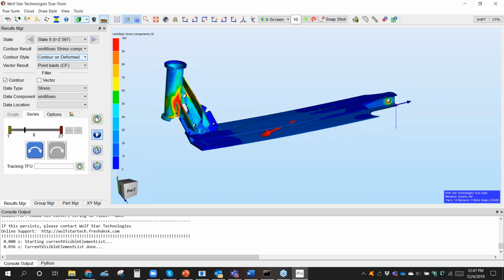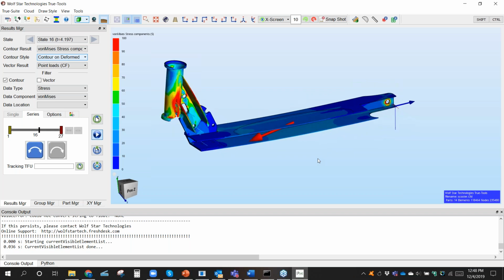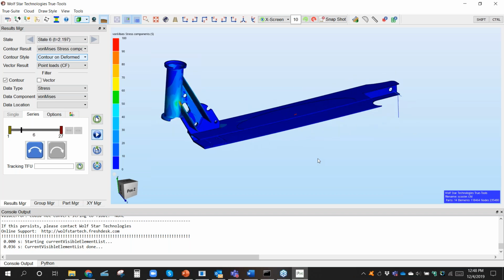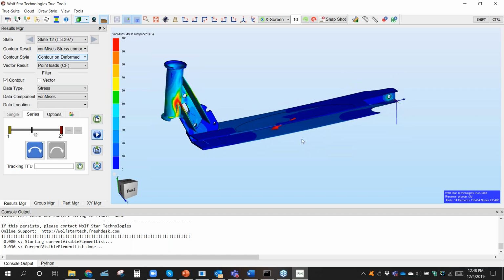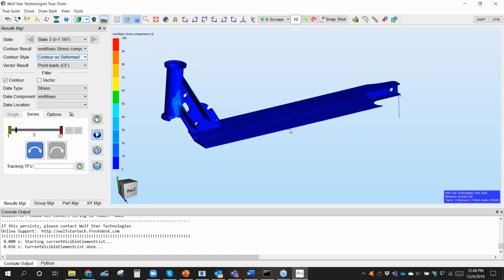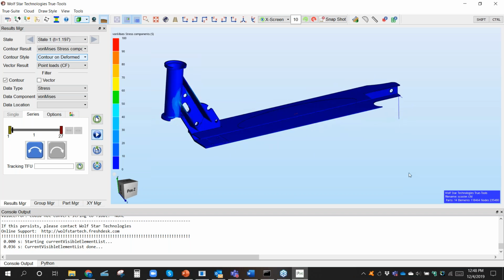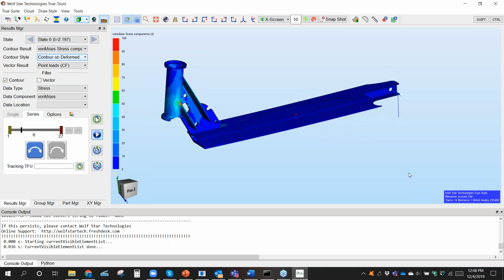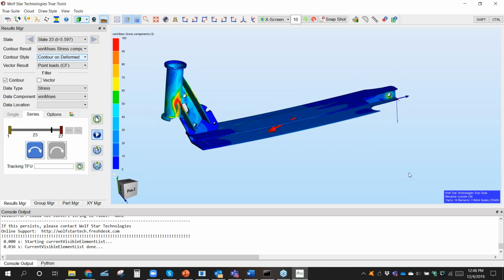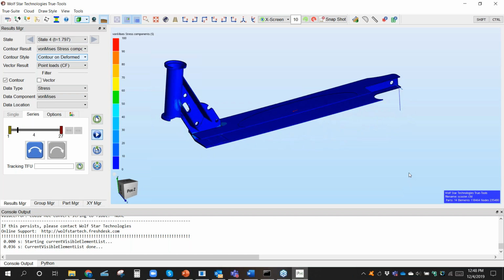Well, this Razor scooter is a perfect example of contact nonlinearities, right? So the way we deal with a contact nonlinearity is basically you introduce a unit load at the point of contact. So in my example here, my nonlinearity is at the foot, right? The foot can go on or off. So I've got a unit load case at the foot, actually X, Y, and Z directions to handle all the contact directions there. And on the tire patch, I've got loads to handle the tire patch. So you basically model unit loads at your contact locations. And if there's no contact, that unit load will be zero. It will be calculated as zero. And if there is contact, then you'll get a value for the contact. So it's really that simple. It's just part of how we do it.